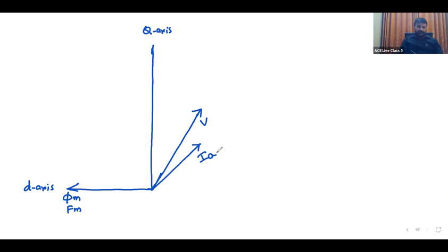All phasors are rotating counterclockwise. Then E leads V. IA, I am taking a lagging power factor. This is IA RA, correct? Yes. I am adding it to V: V plus IA RA. The IA RA drop is in phase with IA.